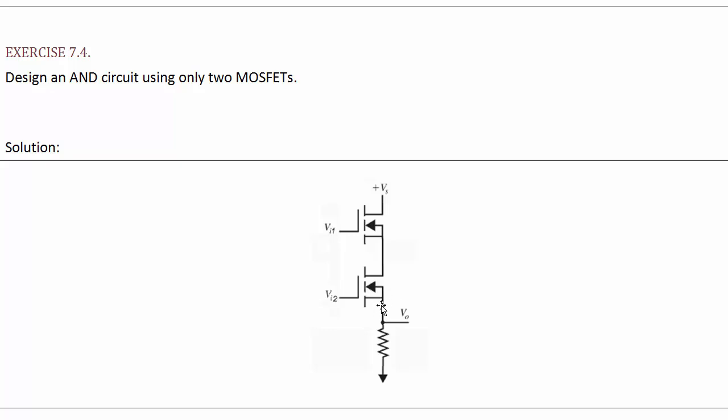A way to remember that is the arrow shows which way the charge carriers are going to flow in the channel creating region if you put a high voltage there. So if you put a positive voltage there, it means that you're going to have charge carriers flow in. So that means that they're N-type, and so this is an N-channel MOSFET. The P-type MOSFET has arrows pointing out, which means positive voltage removes any channel that was there. Okay, now back to the issue at hand.